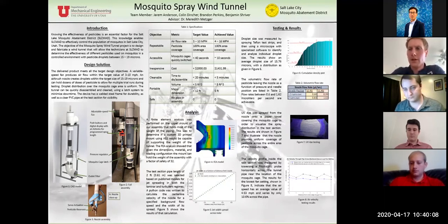And in the figure to the right, figure 8, you can see the measurements that we took during this test. One line represents one orientation when we took measurements, and another line represents another orientation. The first orientation was when the pitot-static tube was perpendicular to the adjustable speed fan, and the second orientation was when the tube was parallel to the adjustable speed fan.